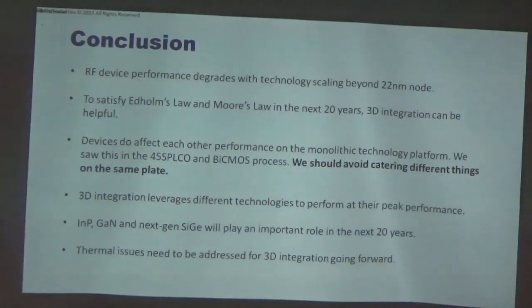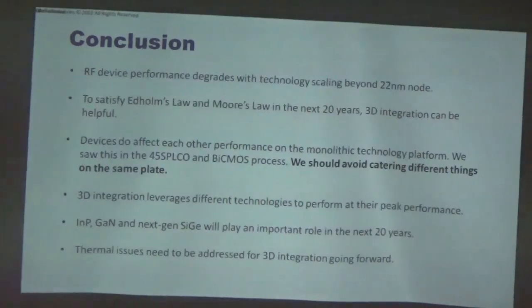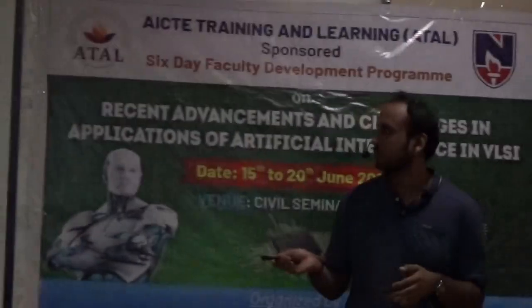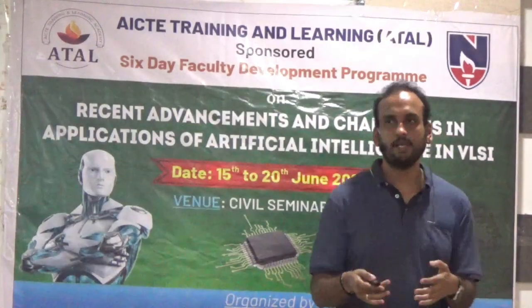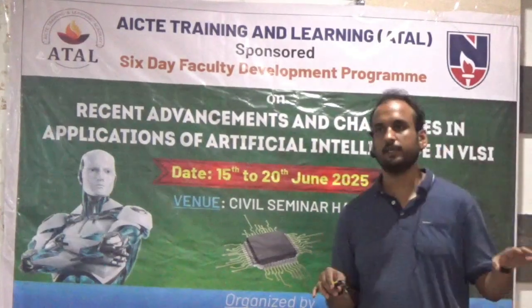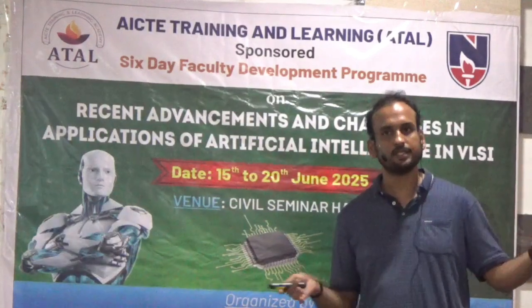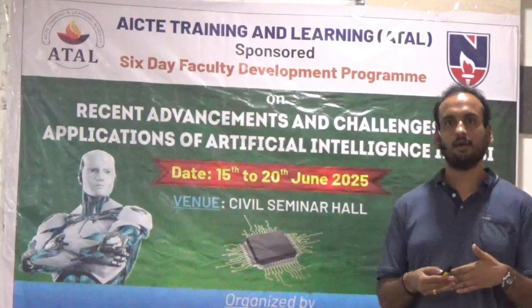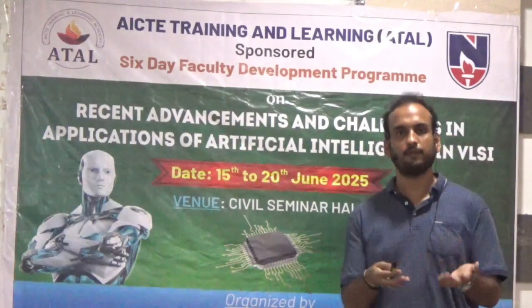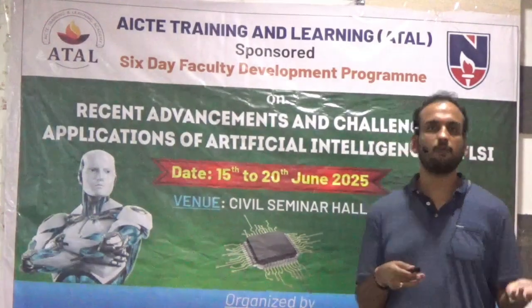So 3D integration is one way where you can increase the number of devices or transistors over the same area. And we have seen that if you try to accommodate all the different devices in the same IC design, it will impact their performance. So let us not cater everything on the same plate. Let's distribute it. Let's make different devices for different applications and use 3D integration. And we have seen that 3D integration not only gives you a cost benefit, it also has a performance benefit.